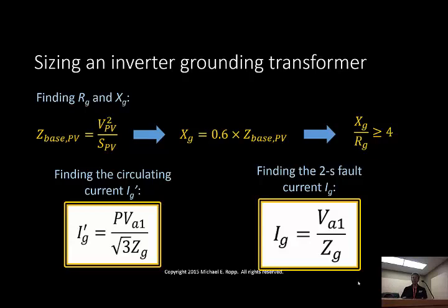What happened? Well, as you might imagine, there are a couple of assumptions that are baked into this analysis. One of them is that we maintain 120-degree phase angle separation. One of them is that the imbalance is roughly symmetrical. In other words, if phase B is in the middle, phase A is 5% up, phase C is 5% down. Neither one of those is strictly true in the field. So we ran a big parametric set of simulations to figure out how much difference does that make.